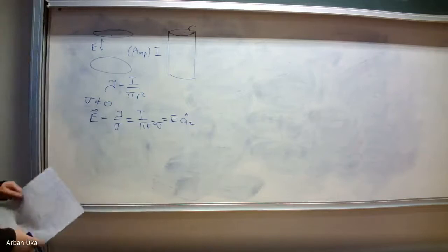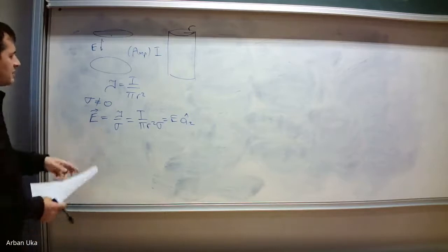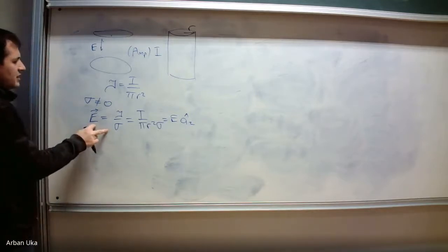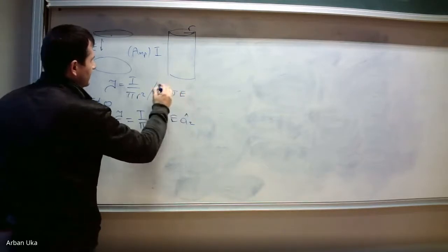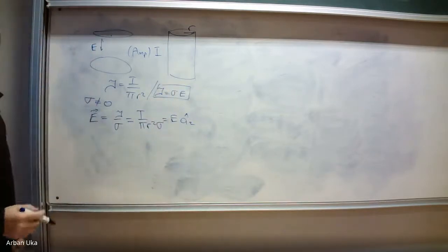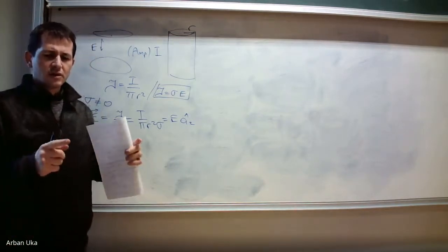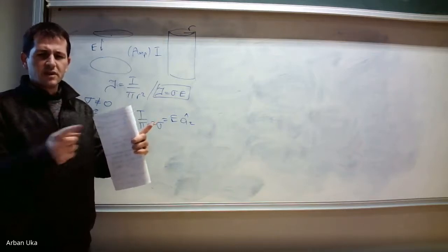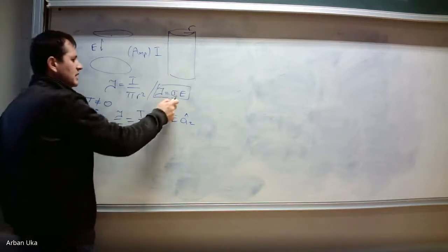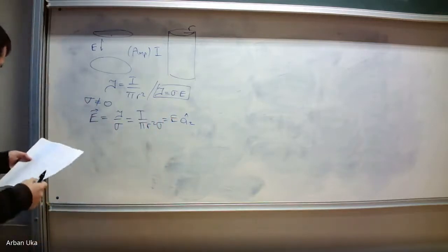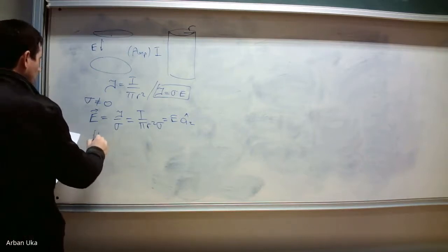So in a wire, we have an effective electric field. Why is this? Because we know that in conductive materials, J is sigma E. It is an external electric field, because that's how we apply the current in a circuit. We connect a wire with a potential difference, so we create the electric field over there. If it is conductive, we multiply the electric field with sigma, and that's what we get. So this is the J, and then we can also find similarly that the H is going to be the same thing.